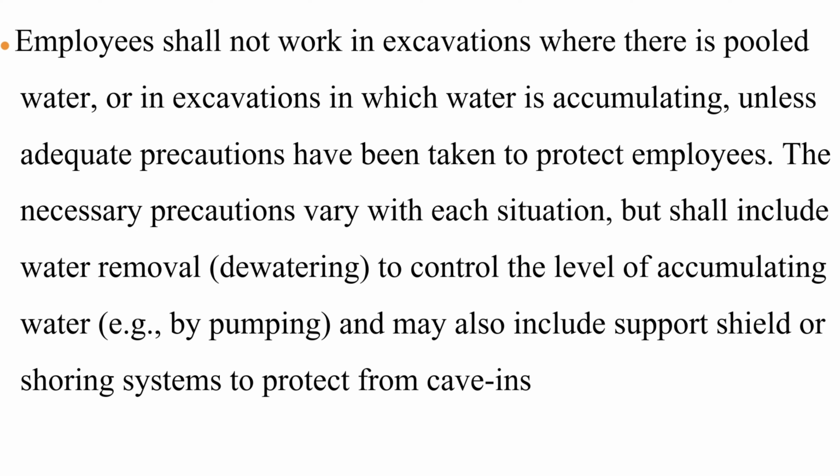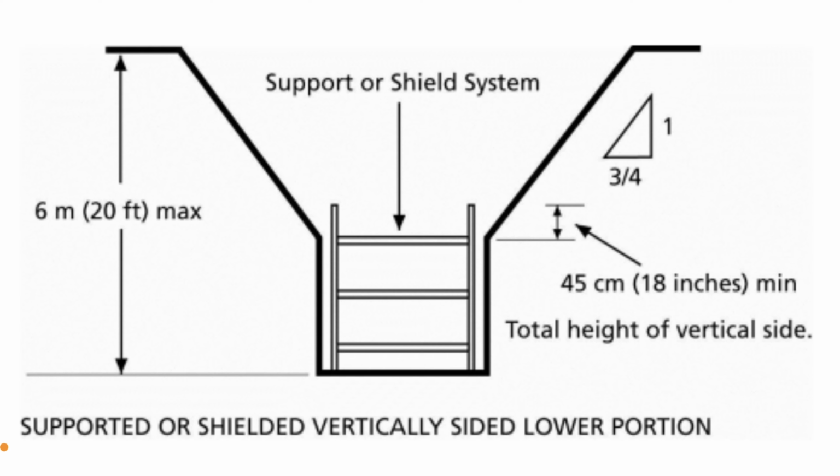The necessary precautions vary with each situation, but shall include water removal, dewatering, to control the level of accumulating water, for example, by pumping, and may also include support shield or shoring systems to protect from cave-ins.